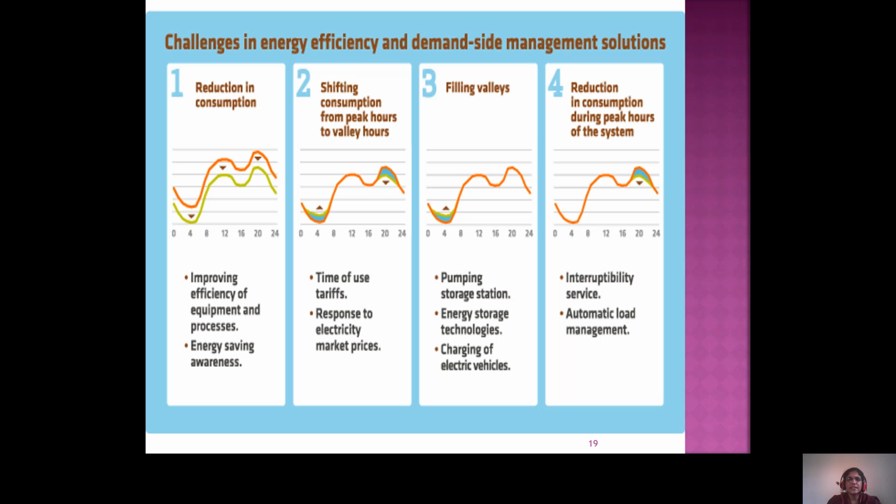What are the main advantages of demand side management? It is environmentally friendly. Load can be matched to variable renewable energy available, with lower generation and transmission cost, lower transmission and distribution losses, reduction in spinning reserve cost, less involuntary load shedding, more consumer growth capacity, better maintenance opportunities, and more availability, that is, fewer blackouts.